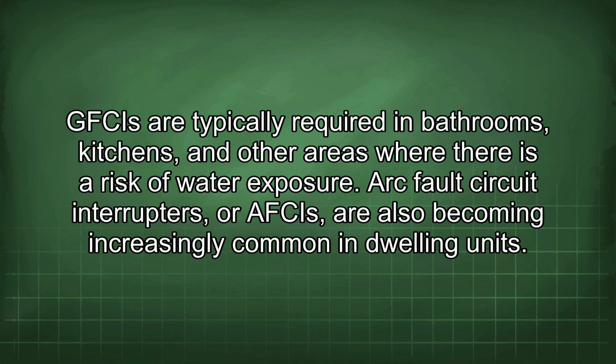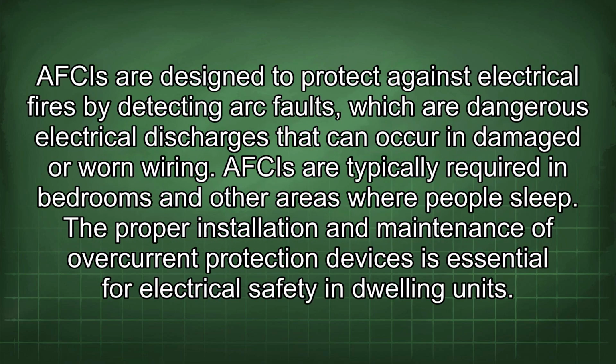Arc fault circuit interrupters, or AFCIs, are also becoming increasingly common in dwelling units. AFCIs are designed to protect against electrical fires by detecting arc faults, which are dangerous electrical discharges that can occur in damaged or worn wiring. AFCIs are typically required in bedrooms and other areas where people sleep.